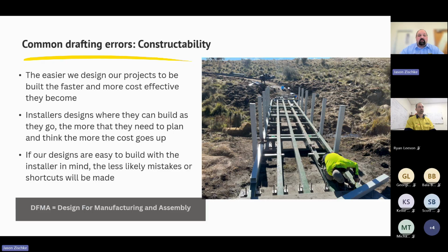So you'll find that a lot of these connections have a lot of flexibility for when things go wrong on sites. When you're thinking about your designs, you want to be thinking, what happens if a tree root is right where I need my pile, and that needs to move? Does my connection design allow for this change without having to resupply and things like that?